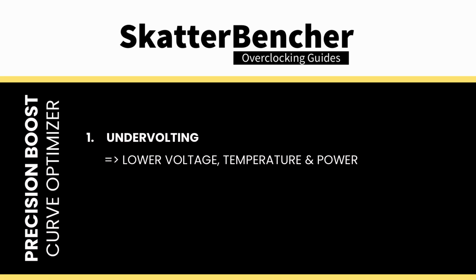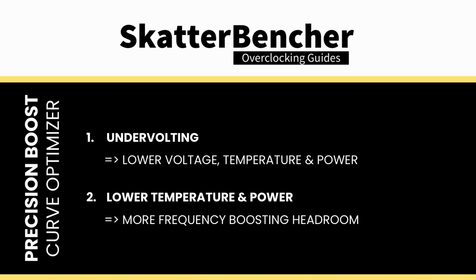The traditional way of using Curve Optimizer is to use it for setting a negative voltage offset, and it helps in 2 ways. First, undervolting lowers the operating voltage, temperature, and power consumption. Second, as a consequence, the Precision Boost 2 algorithm can leverage the additional headroom to boost to higher frequencies. So you tend to get lower temperatures and higher performance. It's a win-win. However, there are a couple of caveats to using Curve Optimizer.